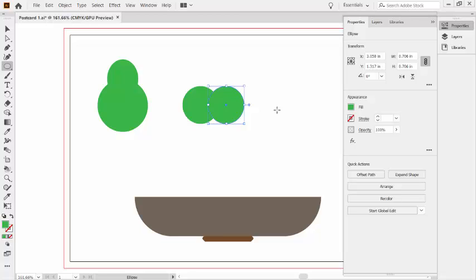Now I want to create another circle by drawing it. I'm going to move my cursor over to the left edge of that left circle until I see the word anchor. And I'll click, hold, and drag down and to the right until I see a magenta line on the right-hand side of the circle, knowing that that aligns it with that right-hand circle. Now, see the widget on the right there? I'm going to click, hold, and drag that over to the left. That creates kind of pie shapes. I don't need to worry about the exact angle just now.